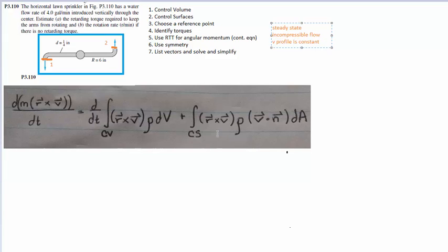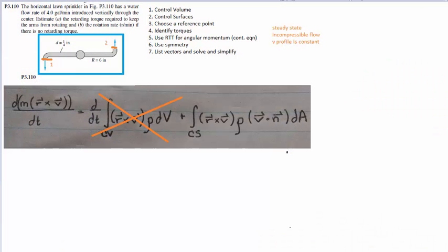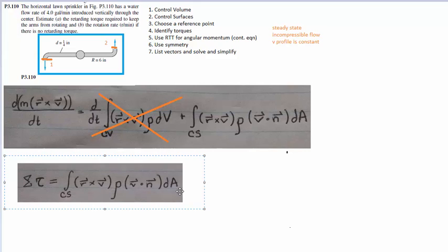We could just pull pretty much everything out and just integrate over dA. So what does that do? Well, it does the same thing as usual. Gets rid of this control volume term that we still haven't used yet. Okay, and then just like in linear momentum, we are going to simplify to this guy here. So it should look pretty similar to the linear momentum equation. We just had the sum of the forces over here, and instead of V, now we have R cross V.